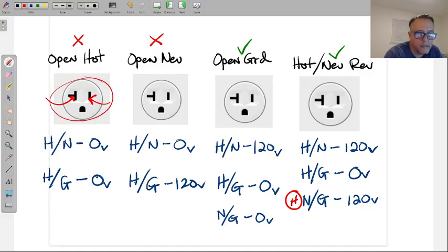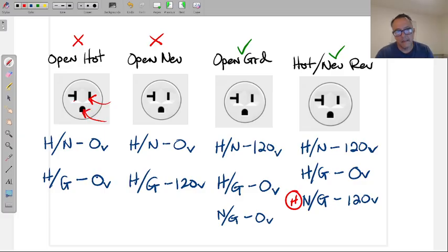So here I'm measuring, I got no voltage. I also check between the hot and the ground, and I'm getting some weird stuff here, and I assume no hot. And now I start to go into the process of solving this as though I have an open hot or an open neutral, whatever. But it is actually a damaged receptacle. That's not from the terminal points where you've landed the wires to the actual receptacle prongs. You're not getting any power flow.